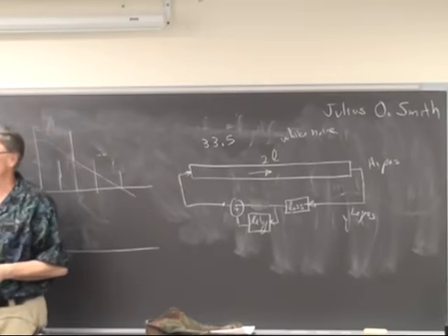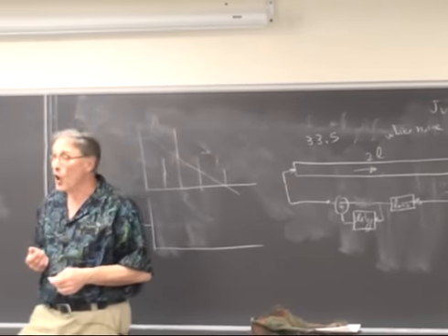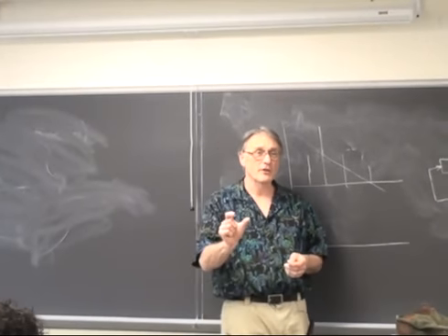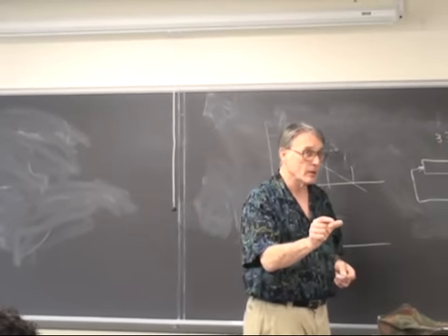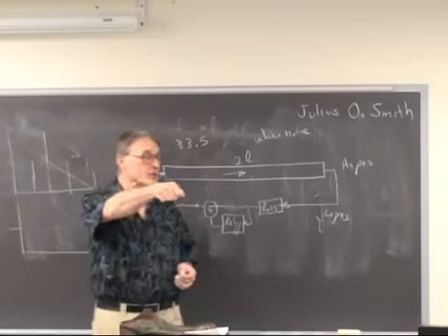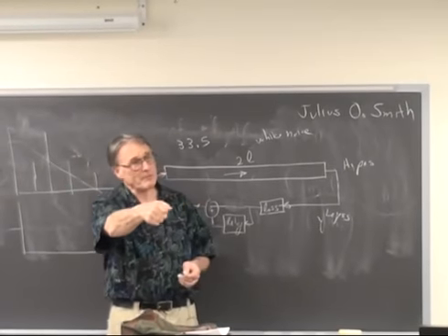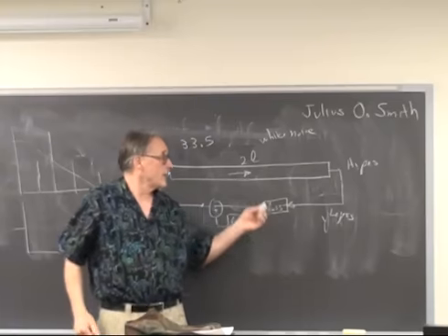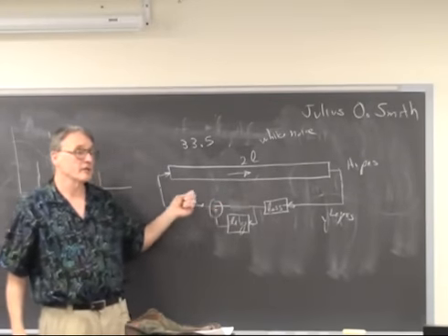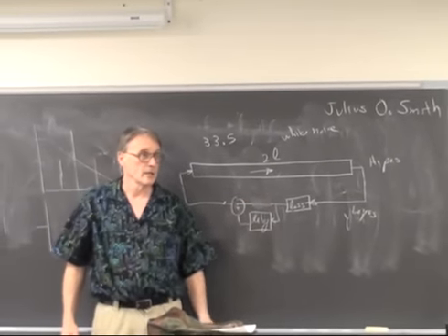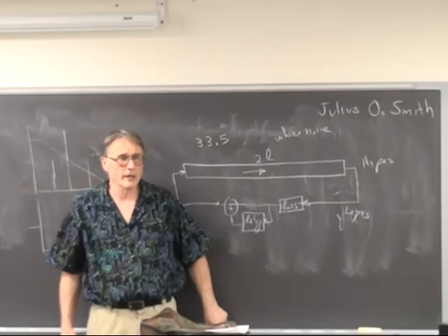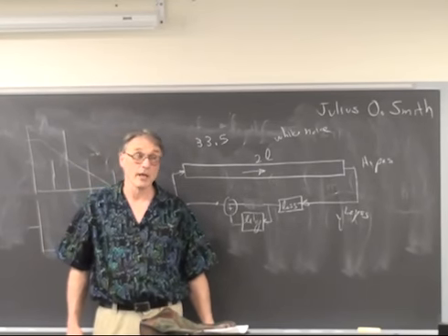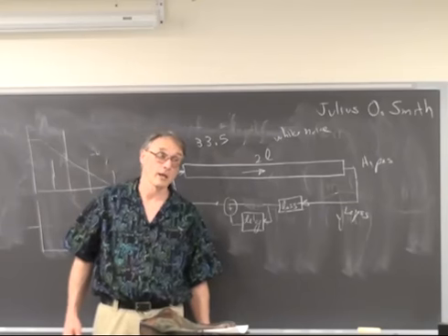You use a phase shifter, an all-pass filter, with a maximum phase shift of 1 sample, and then you can tune fractional samples by mixing the phase shifted and the unphase shifted version to get any exact frequency you need. And I think the examples online do that on the DSP page. The DSP page is linked off of Lab 3. Might want to start reading that.